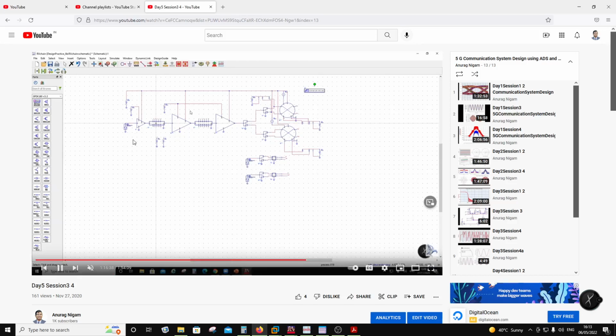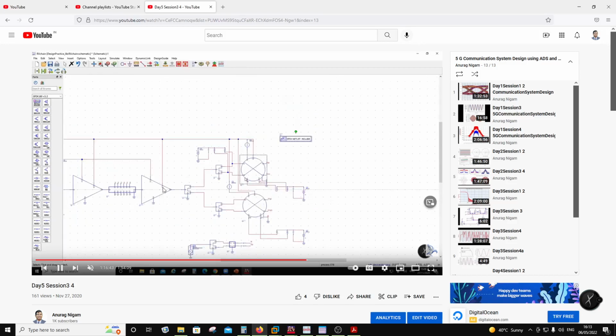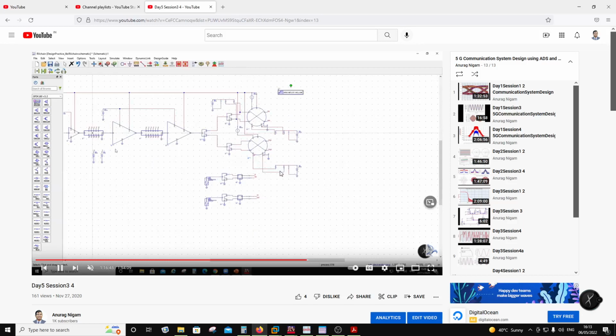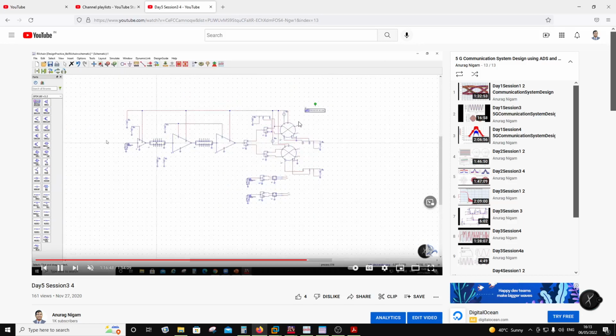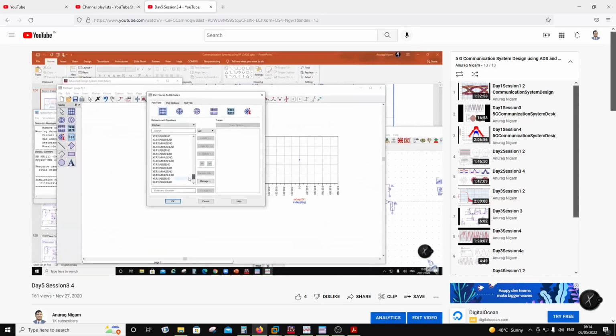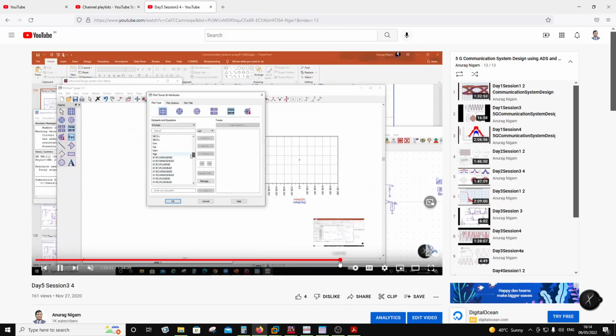So basically, this is the receive section. This is the receiver, and there are the I and Q channel mixers over here, and your VCO input is over here for quadrature generation. Now here there will be a PLL. If you go further, I would show you a transmitter also, and I have done the entire channel between transmitter and receiver, and then evaluated the EVM and ACPR.